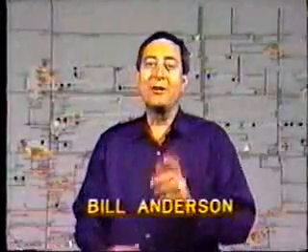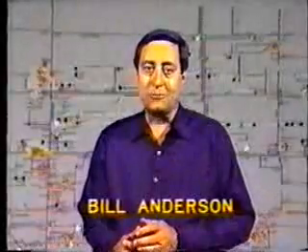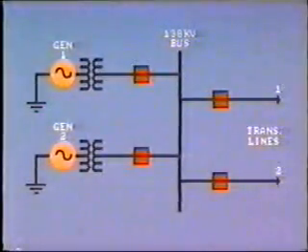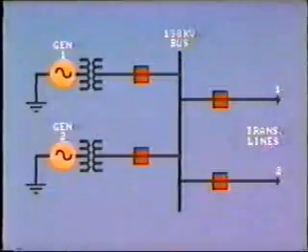In this video, we're going to look at various schemes which are used to protect buses. We all know that the bus is a very important part of the power system, as it must be used at every junction point of lines and feeders. Normally, a bus will have several power sources feeding in and several lines feeding out of the bus. The most simple arrangement would be, for example, at a generation station where, say, 2 generators feed into the common bus and 2 transmission lines transfer the power out of the bus into the system.